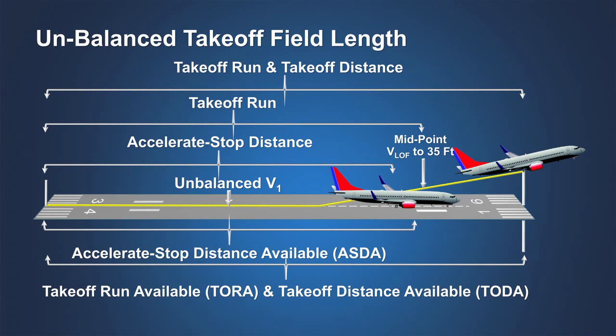However, the use of unbalanced takeoff data is an involved process. Use of an airplane performance planning software tool or an airport engineering service that furnishes a runway analysis is recommended.